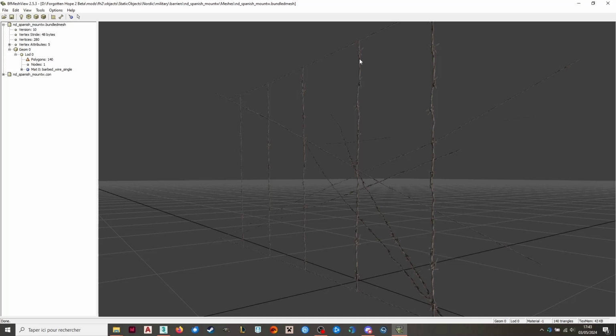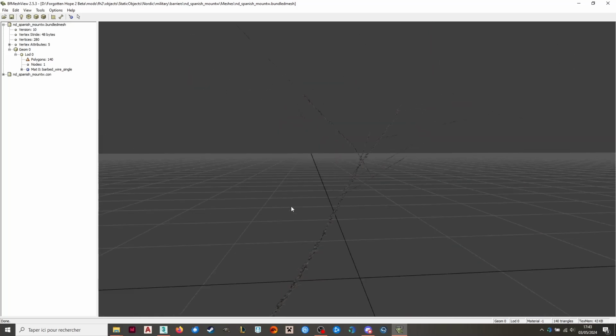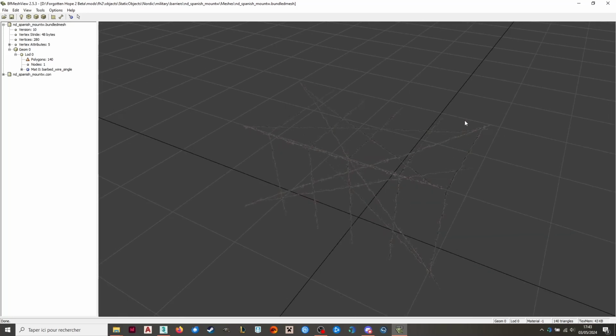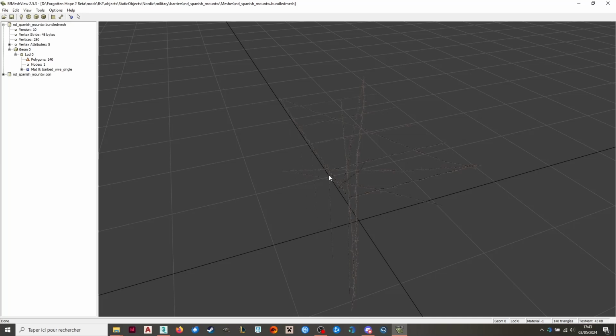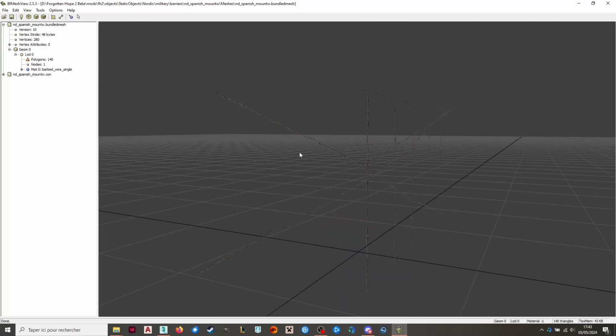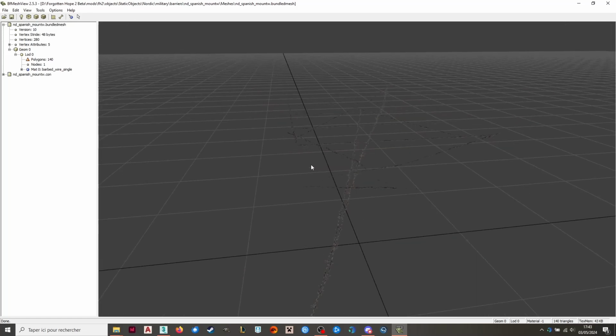What I mean is that in 3ds you make a face, you put the texture on it, but it will only show on one side. It won't show on the other side. So you will have to duplicate everything you've done so far, sorry, and invert the normals. So just flip the face on itself, so it can show from the other side.